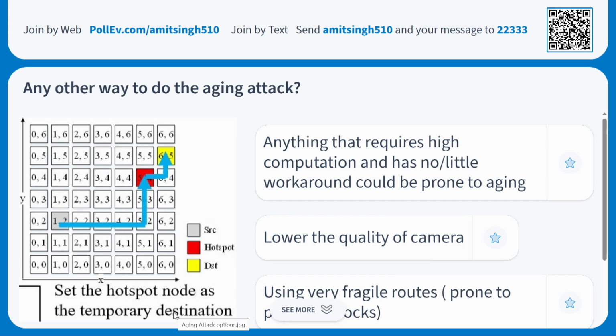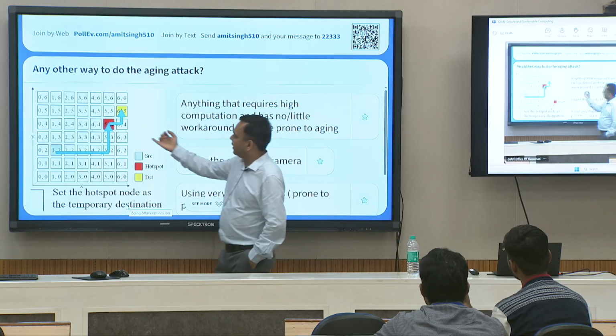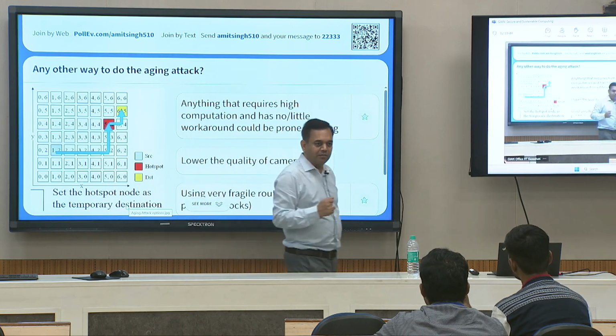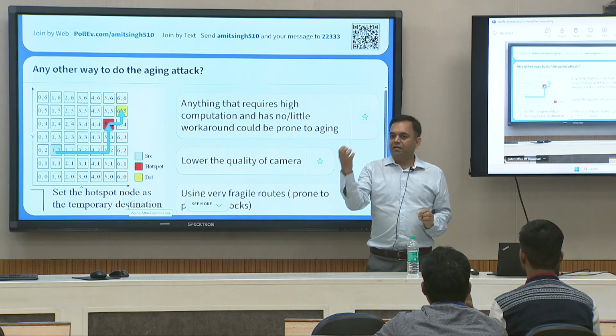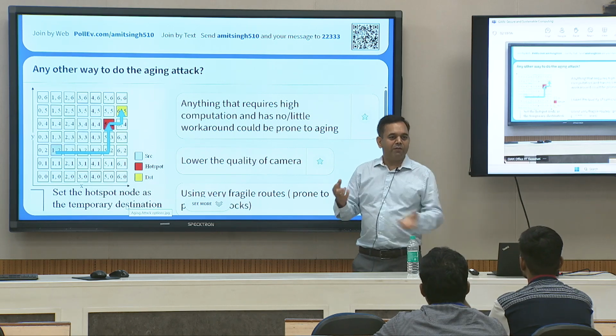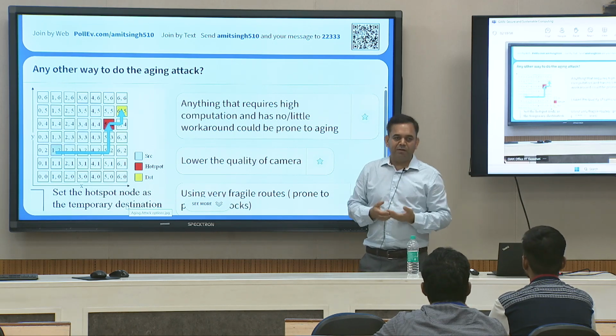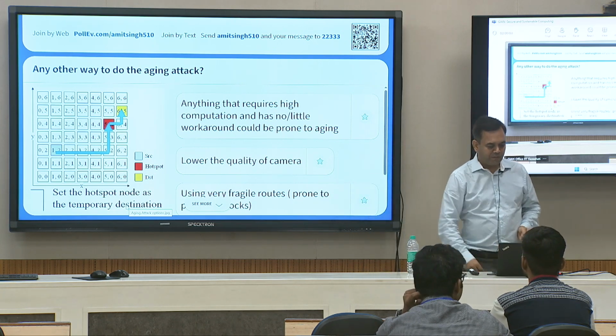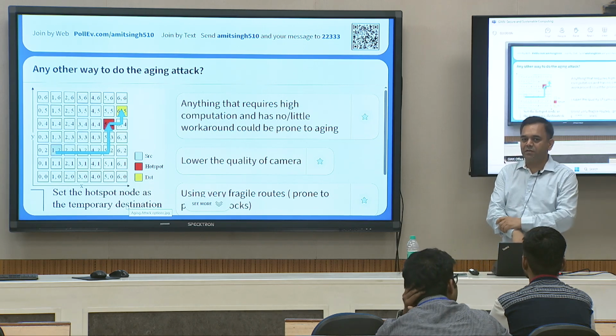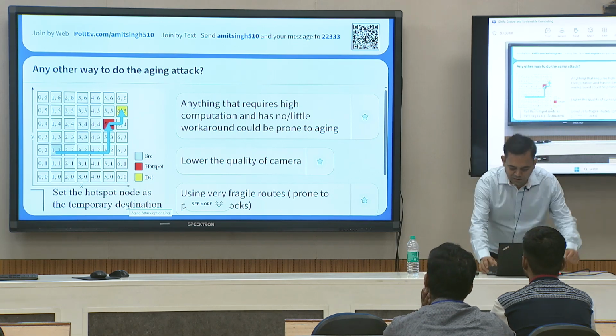Recall this hardware Trojan thing. What exactly was it doing? It's related to basically the first point. You can increase the power level, but maybe you can have a hardware Trojan in one of the routers, and when the power requests are going to the global manager, this one can always request more and more power, and it can heat up and then bring the whole system down. That's one way. Hardware Trojans can be used. Good.